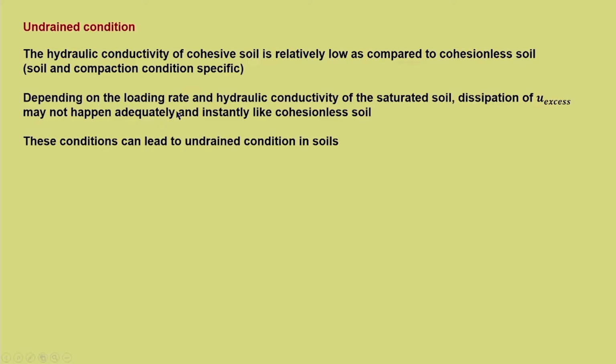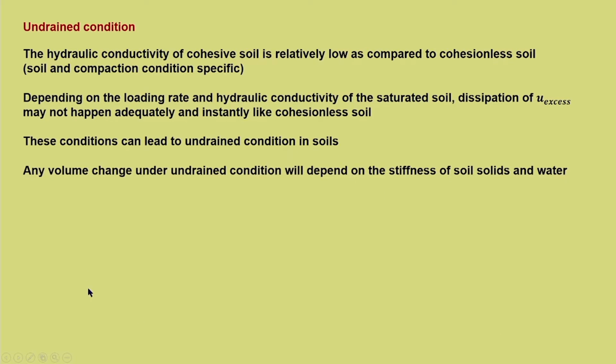Now, depending upon a fast loading rate and low hydraulic conductivity, also the access for the water to move out, these three conditions can lead to undrained conditions in soil. Now, the question associated with undrained condition is, yes, we understand water is not allowed to move out, excess pore water pressure will remain there, so what? Now, what is the net effect of undrained condition? When we say it is an undrained condition, what should we understand from it?